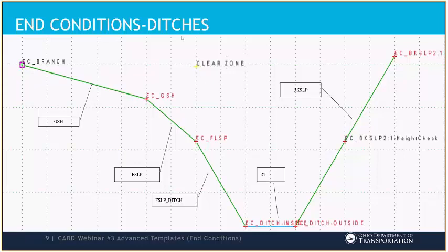In other situations, you really don't need three or four slope pieces, if you will. In those cases, you have a grade shoulder slope, and then you go straight into a ditch. So what I wanted to make sure we handled automatically is that if you're switching between those conditions for some reason, the pieces just connect automatically.